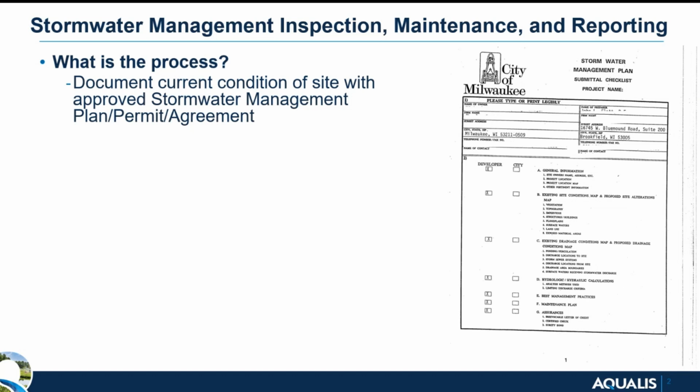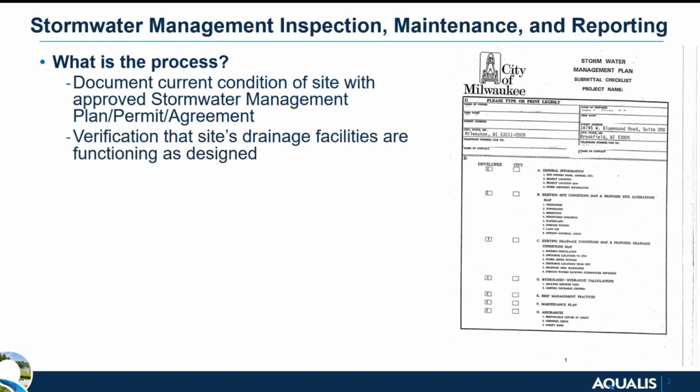And I use those three terms interchangeably because they are the common practices that we see municipalities use to deliver these programs, and they'll be the basis for an inspection and any maintenance requirements. So those are really the documents that we are using as consultants. Through the inspection, we want to verify that the site's drainage facilities are functioning as they were designed. And we can do that a number of ways.